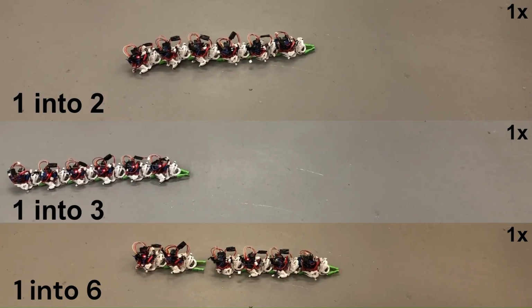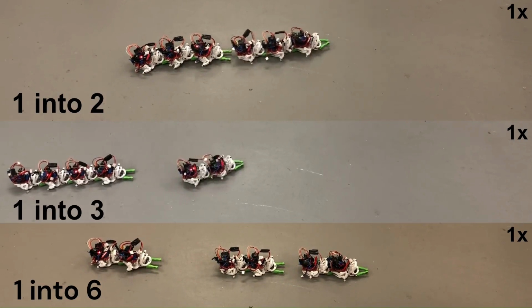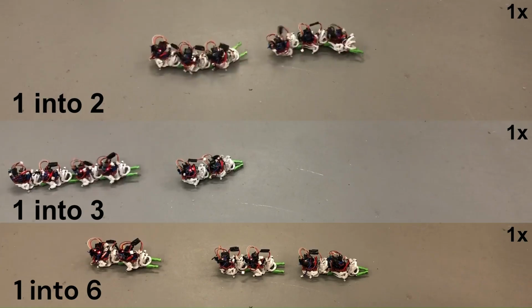The mechanisms were implemented in a modular Caterpillar robot. Each segment contains only 2 brushed DC motors. Segments are chained together with compliant grippers. The segment articulation mechanisms are used to steer the robot by rotating in the pure yaw region of motion. The compliant gripper on each segment can be opened by actuating a shape memory alloy through electrical heating. This allows the robot to reconfigure into chains of various lengths, which can each move independently.